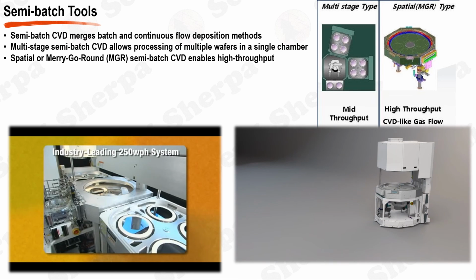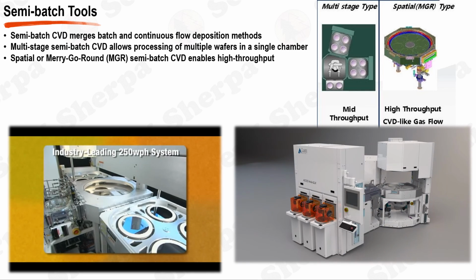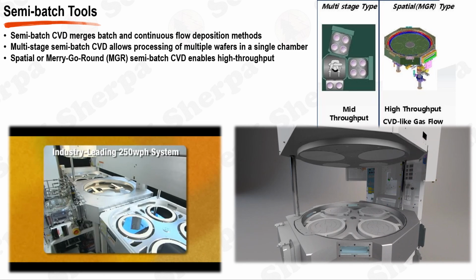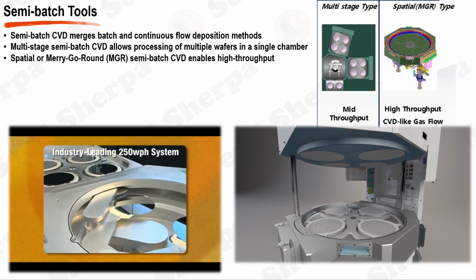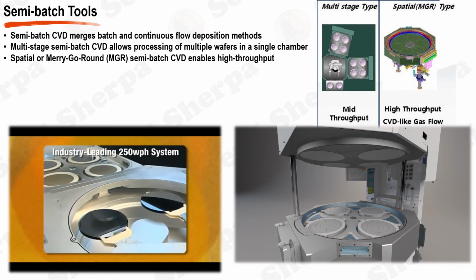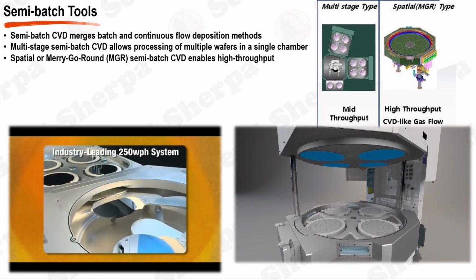While semi-batch CVD does involve complexities in managing the precise timing and rate of gas additions and removals, it offers the potential for enhanced control over film deposition, uniformity, and efficient material usage. The nuances and advantages of semi-batch CVD processes are crucial for optimizing various thin film deposition applications.